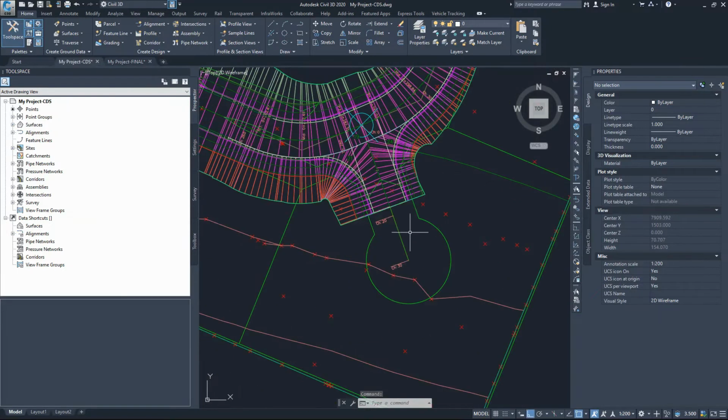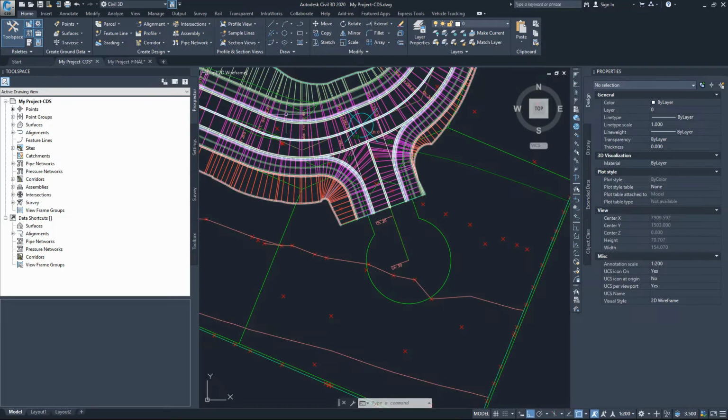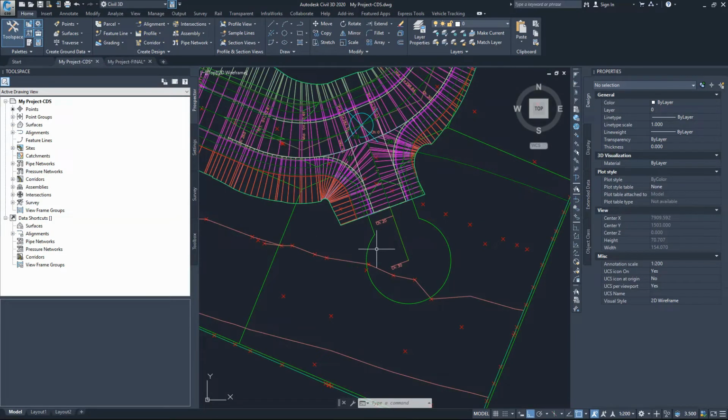Okay, so going back to our file, the first thing we need is to create that shape. Before I start working on the Cul De Sac, I've got one step to do. Looking at the size of the road I gave you, that road is about 5 meters narrower than the other roads. It's just a secondary road, so it's about 10 meters wide, whereas all the main roads here are about 15 meters wide.